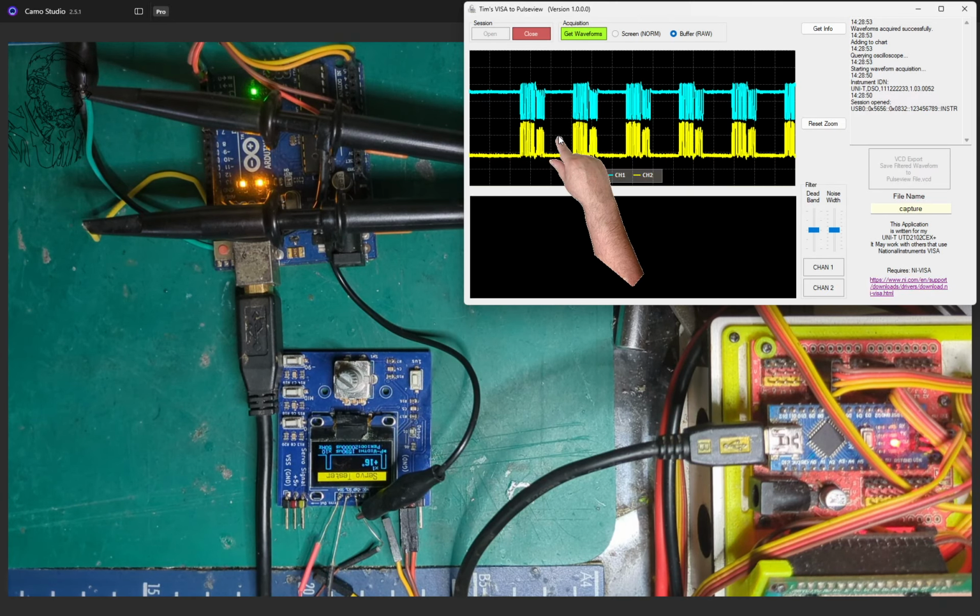Because I need two channels, the size of memory is halved, half the memory for one channel, half for the other. So when you're buying oscilloscopes, and it's got this amount of memory, just remember, if you're using two probes, that memory is shared between two probes. I'm rambling again, aren't I?